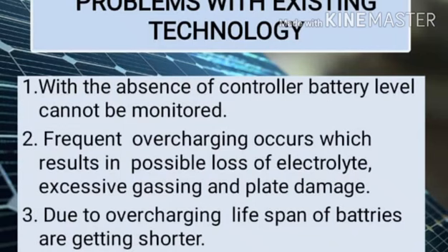Further, we will talk about the problems with the existing technologies. The problems are that with the absence of a controller, battery level cannot be monitored. Other problems are that frequent overcharging occurs, which results in possible loss of electrolyte, excessive gassing, and plate damage. Due to overcharging, the lifespan of the batteries gets shorter.